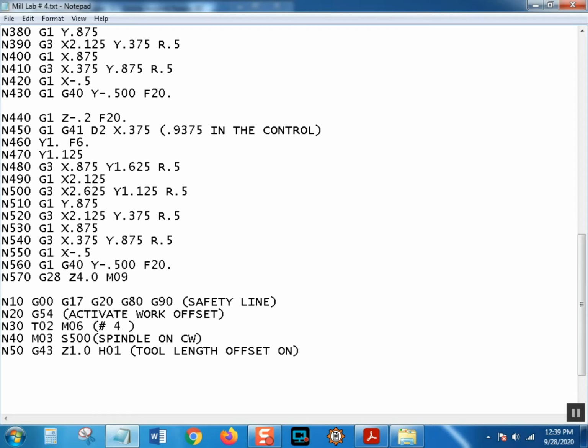I'll go back and make it capitals. Hit that caps lock button now. Might as well get that going. The bane of the CNC. There we go. So I got a number 4 center drill. This stays the same. That stays the same. I changed it to tool 02 because tool number 2 is going to be my number 4 center drill. And of course I got my M06.